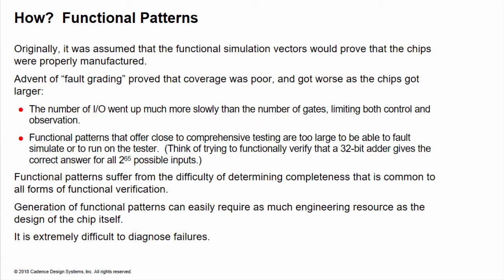This makes a lot of sense. If the simulations are sufficient to ensure that the design is correct, then they should also ensure that the chip was manufactured correctly. Unfortunately, that is not sufficient. There's still no generally accepted means for determining the completeness of functional verification. The advent in the early 70s of the stuck-at-fault model and fault simulation, also called fault grading, found that functional verification patterns provided poor coverage at best.